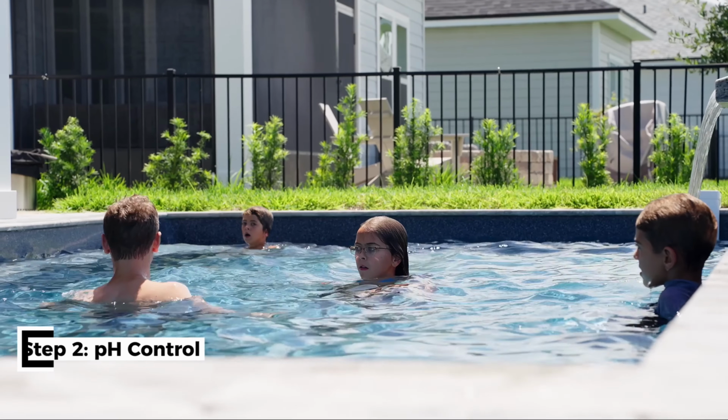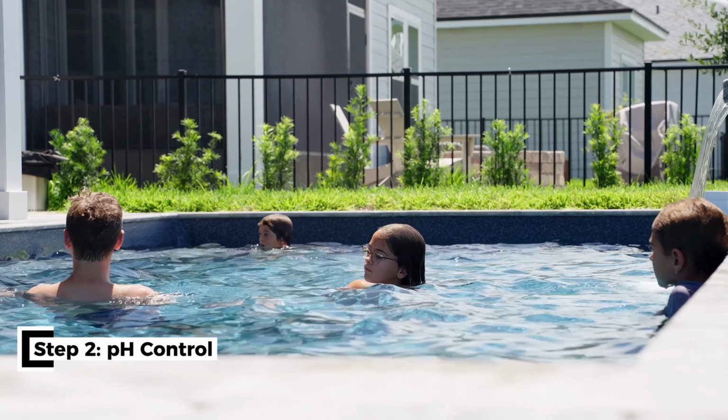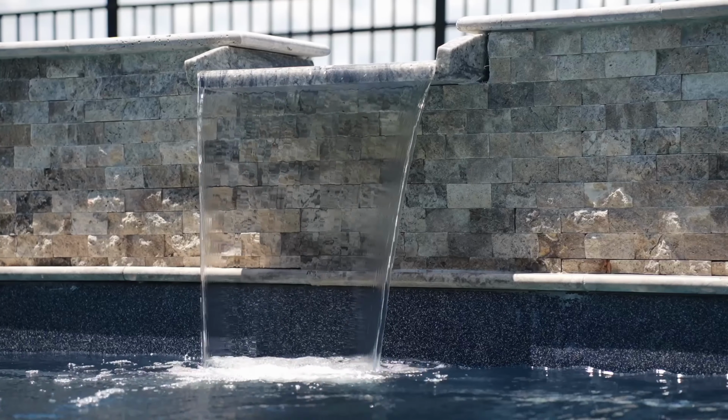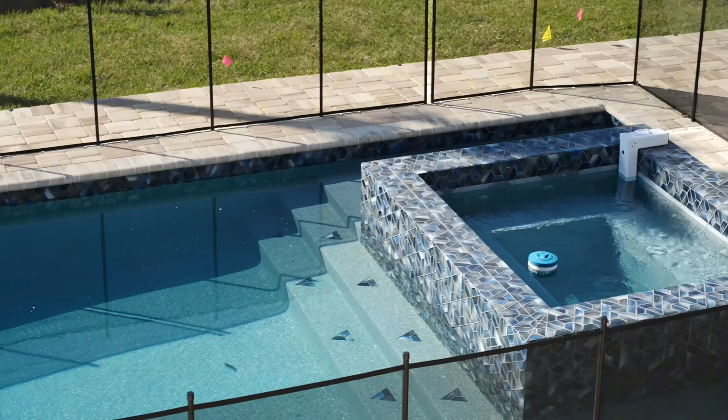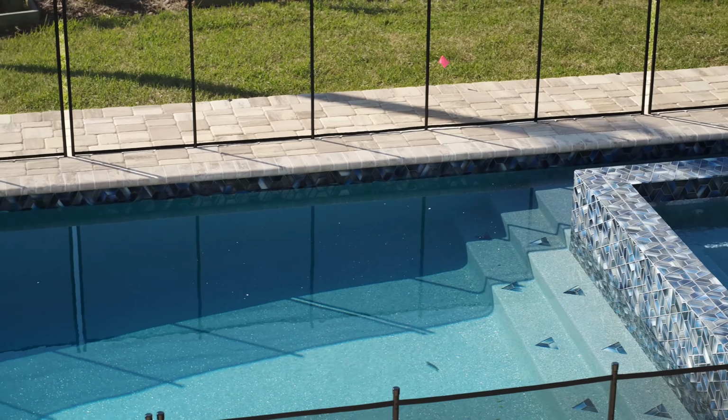Step 2, pH control. pH is a measure of the relative acidity and alkalinity of the water. It is very important to keep your pH levels between 7.2 and 7.8 to avoid many of the problems that can occur with your pool surface.